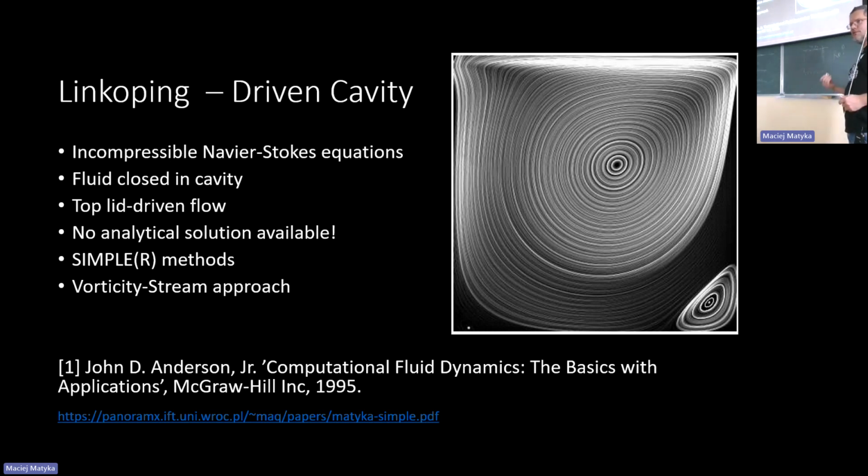It's an interesting physical phenomenon because, apart from the main vortex, secondary vortices may appear in the corners. With the Reynolds number, there can be even third-degree corners, fourth, and so on. There is a cascade of corners.